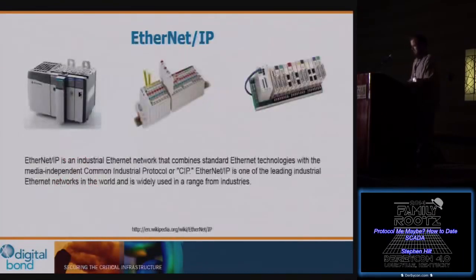With that, let's move on to Ethernet IP, the first one that we are going to talk about today. Ethernet IP is an industrial network protocol that combines the standard of Ethernet technologies and the Common Industrial Protocol. This is a very popular protocol. On the left, or on your left, you'll see an Allen Bradley Rockwell device, a WAGO in the center, and an Opto22 on the right.